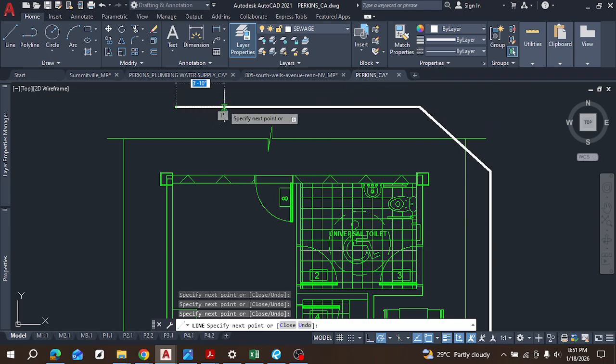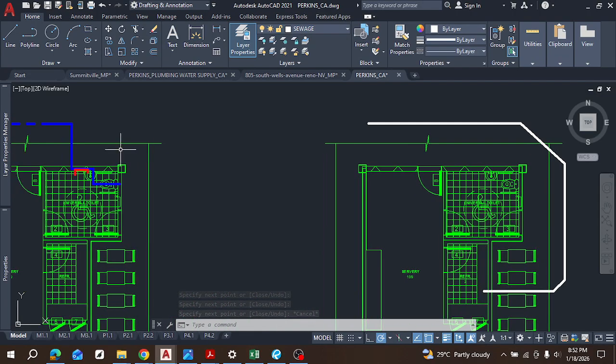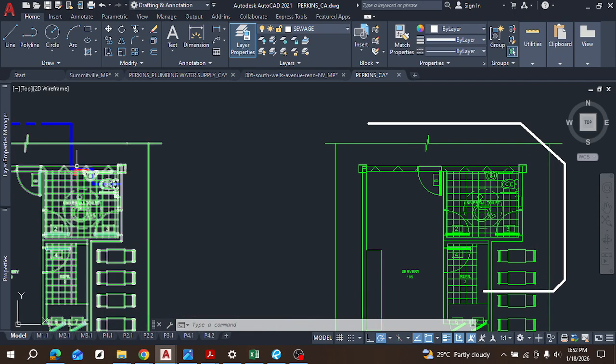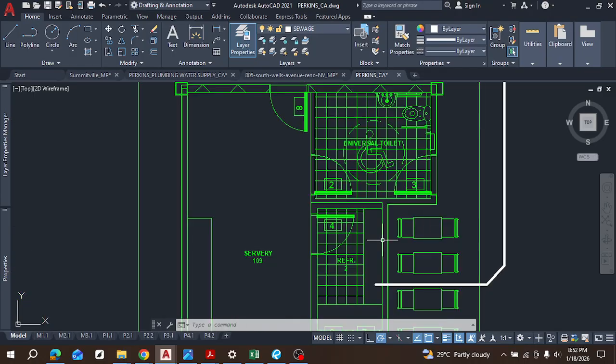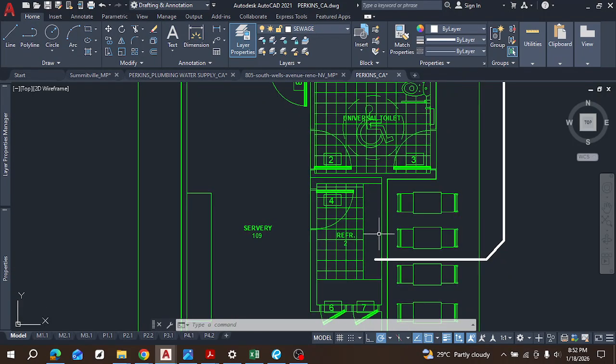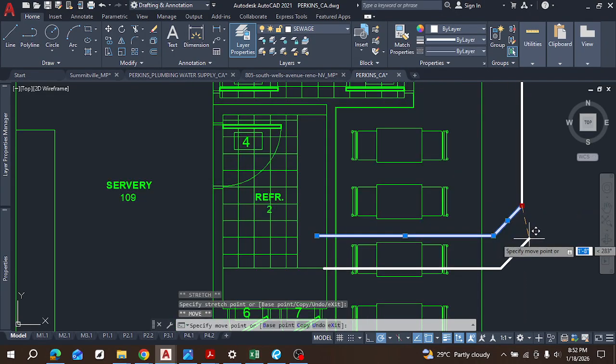That's another thing I didn't mention, right? Usually, unlike cold water lines, which have sharp 90-degree bends because they're under pressure, so it doesn't really matter much, for this one, if it's sharp, this place could be where the water gets to stagnate, right? So it's good to avoid sharp bends. Right, okay, let's move this down a little. Okay, somewhere here.